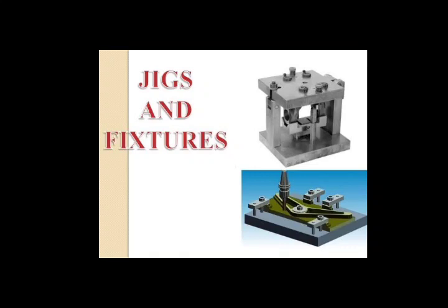Third, type of material used and its properties. Next, accuracy, tolerance and quality requirements. Next, material handling methods. Next, machine requirements. Special tools, jigs and fixtures and methods required. Work area and working condition. So this is called the primary analysis with 8 steps.